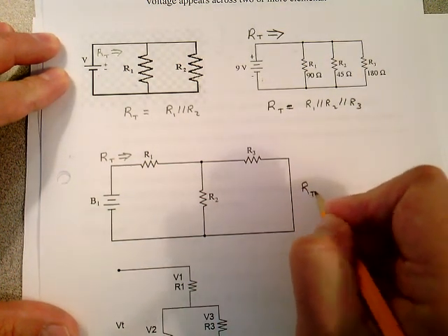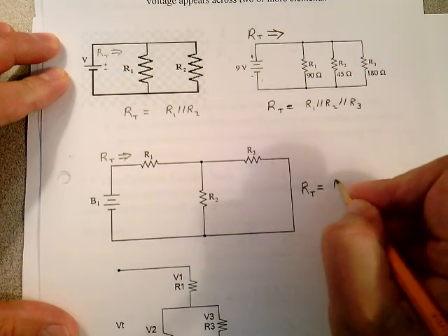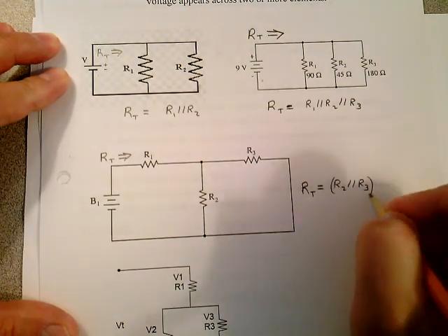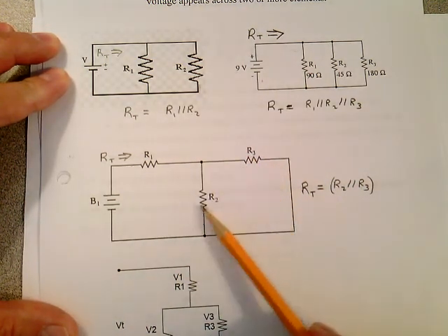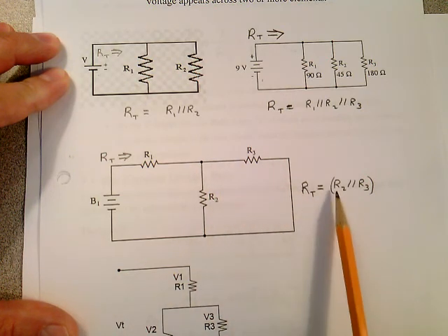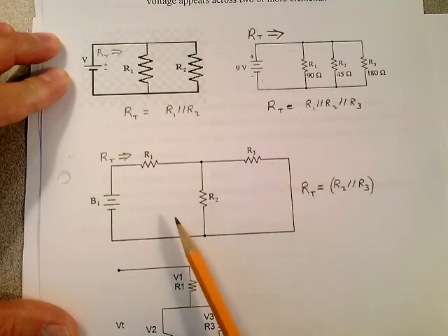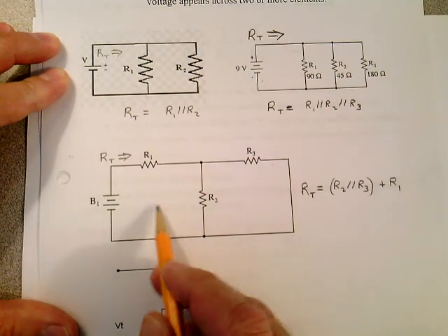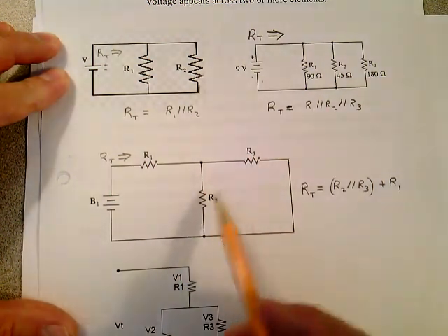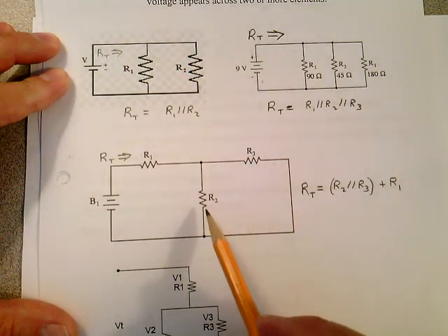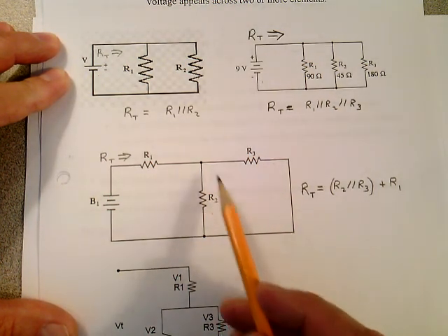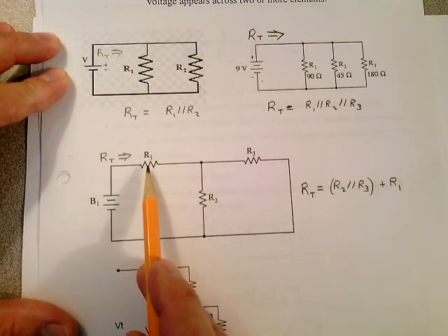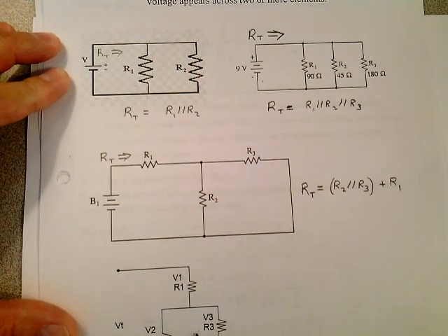Let's write it out here. The total resistance is equal to R2 in parallel with R3. We discussed that. And then once you make that equivalent calculation, you could replace these two. You could get rid of this resistor and replace R2 with this value, whatever it is. We haven't talked about it yet. And then you have to add R1. So the total resistance down here is the parallel combination of R2 and R3, whatever that is, call that R23, one resistor. You can replace these with one resistor, and then it becomes a series circuit, in series with R1.